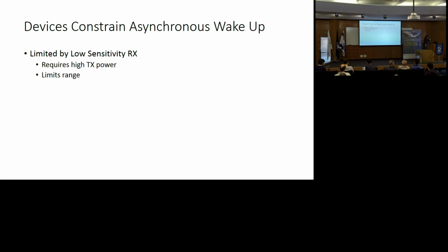So let's talk about this asynchronous version first. This is actually a device problem in my opinion, because these asynchronous wake-up radios are very, very simple things. They're simple animals. They're essentially very low sensitivity radios that exploit a nonlinearity in a device to do what we would call either envelope detection or self-mixing. For those of you who are not wireless people, because that probably sounded like jargon, you're exploiting the nonlinearity in the device to take a signal and mix it with itself. You'll get something at twice the frequency and something at DC. You detect the energy at DC. That's really all you do.